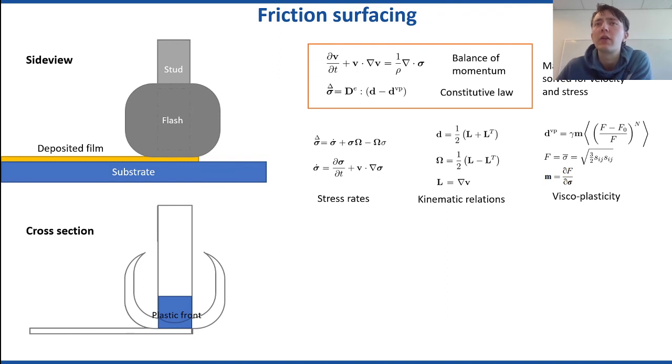And normally, if you do a static analysis of plasticity, then you try to project onto this plane of permitted stress states, and that assumes that we're dealing with an infinite amount of time such that it can settle. In this application, it's precisely the dynamics that are important, so we don't want to assume a quasi-static setting. We don't want to assume that, and that's why the viscosity plays a role here. So plasticity is allowed to flow. We're interested in the temporal response.